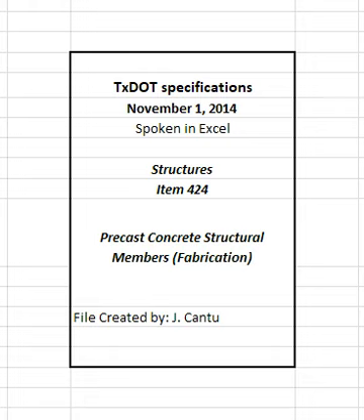and falling unless approved. Concrete may be placed when the atmospheric temperature in the shade is at least 35 degrees Fahrenheit and rising or above 40 degrees Fahrenheit, provided adequate cold weather protection provisions are on site and available for immediate use before placing concrete when weather conditions indicate a possible need for temperature protection. When required, provide necessary covering material or an approved accelerated curing system in accordance with section 424.4.2.7.4, accelerated curing, and do not allow any concrete to remain unprotected for longer than 1 hour after placement.